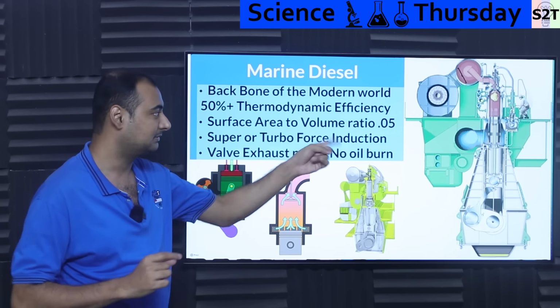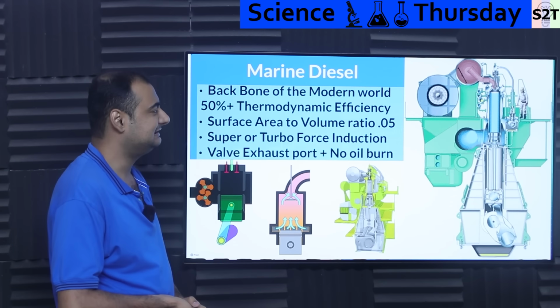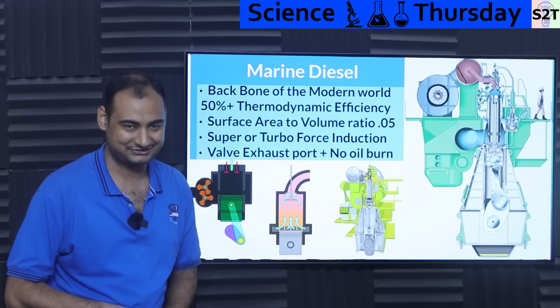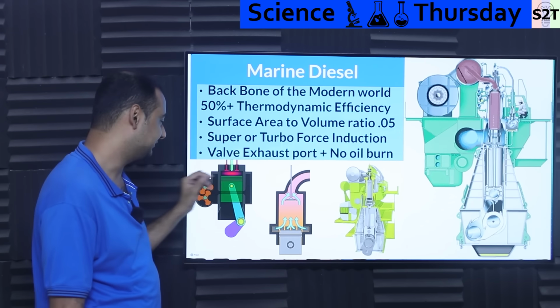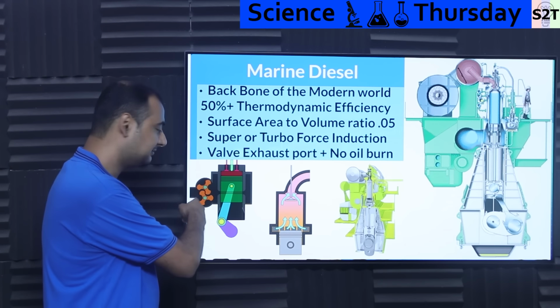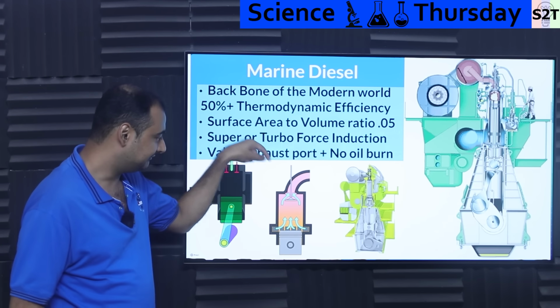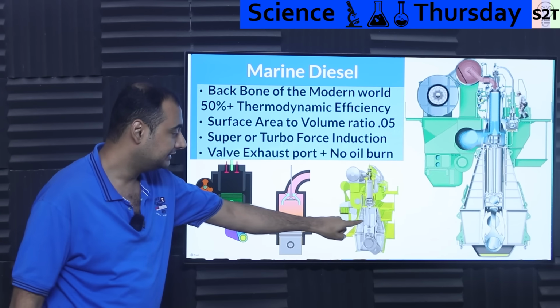Now there is a penalty. These engines are not designed to breathe on their own. They do not breathe. They are technically not even two-stroke because there is no intake stroke. You have to force the intake here. So what we do, either we have a turbocharger or supercharger. Older designs have a supercharger, newer designs all switched to turbo. So you have a blower, and the exhaust valve opens and then the blower flushes the air in through the inlet ports.